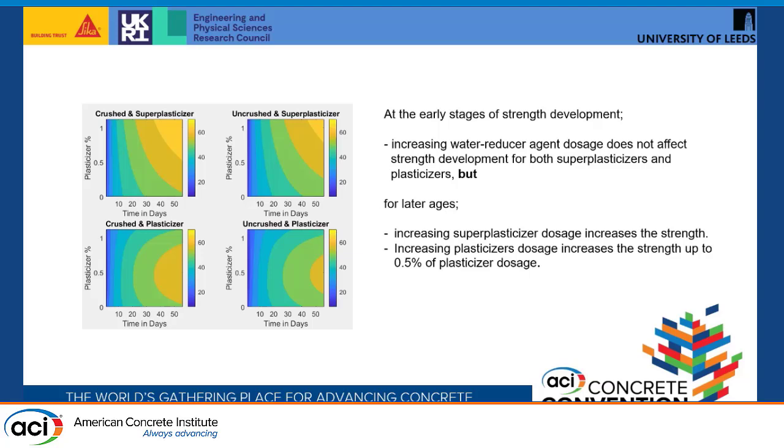Let's move to the plasticizer effect now. Here are some contour plots with superplasticizer and plasticizer. Let's look at the early stages of strength development. As we see, increasing plasticizer and superplasticizer, both of them, in the early stages doesn't give too much contribution to the strength development.